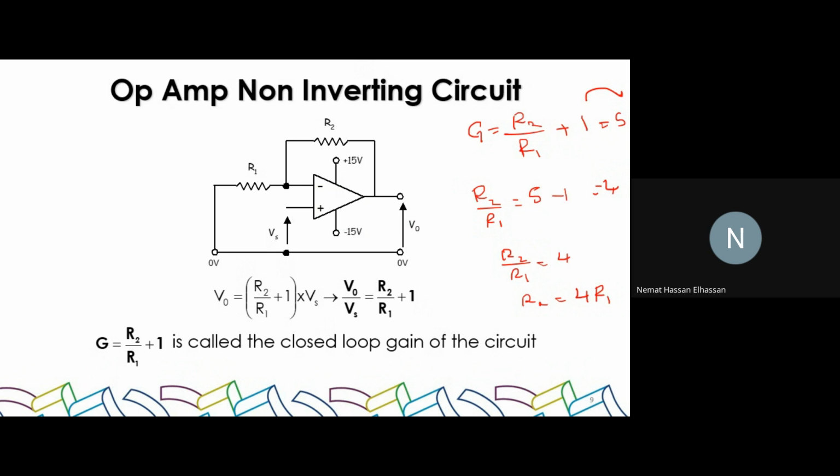Is it clear? Okay. We said the whole purpose of this amplifier, now we learn two ways to build an amplifier. Both will amplify the output, but one will amplify and invert, and one will amplify without inverting. Okay, the whole purpose of the amplifier, we said, and when we design a filter, we want it to be active, which means we want to add gain. And the amplifier's purpose is to add that gain. So how do we design a filter with an amplifier?